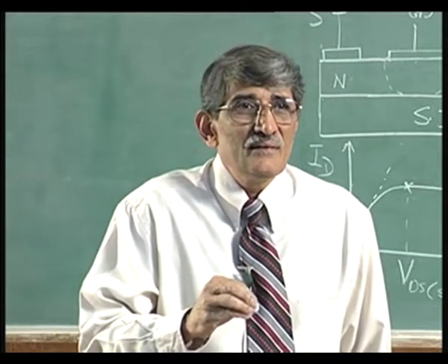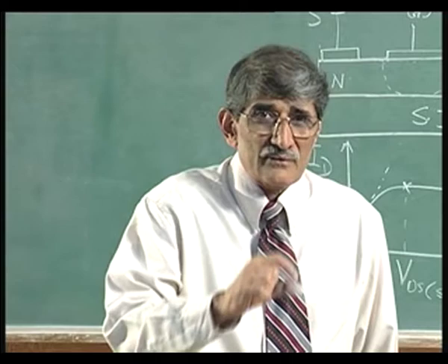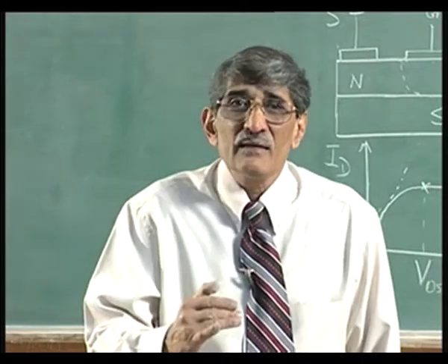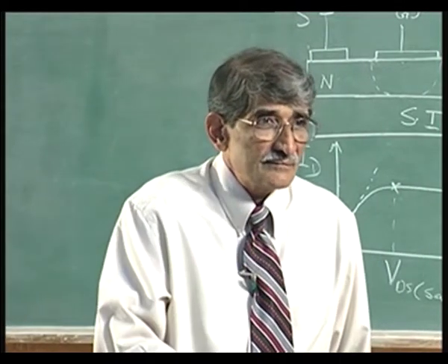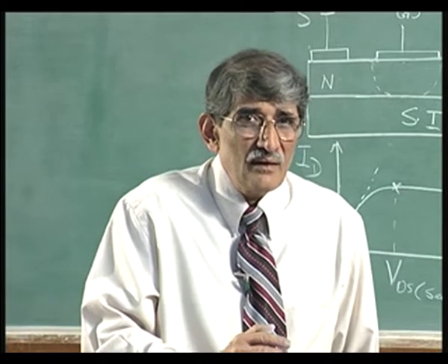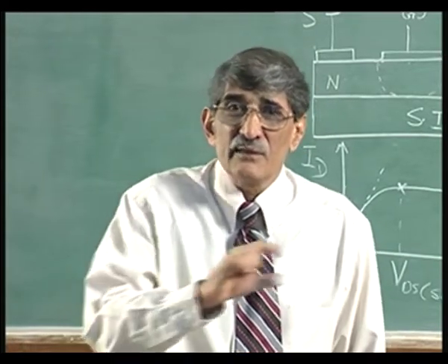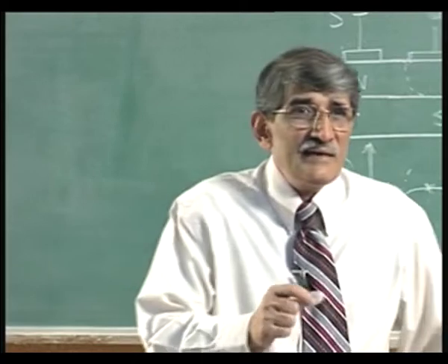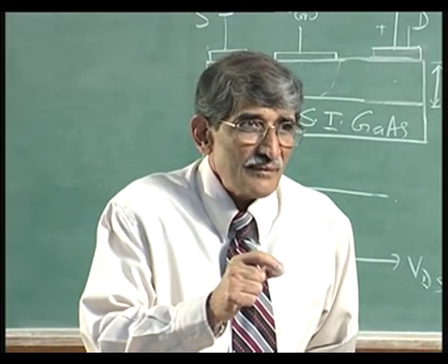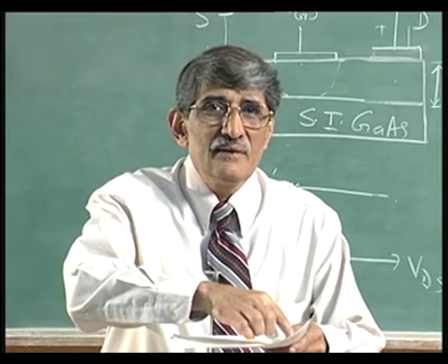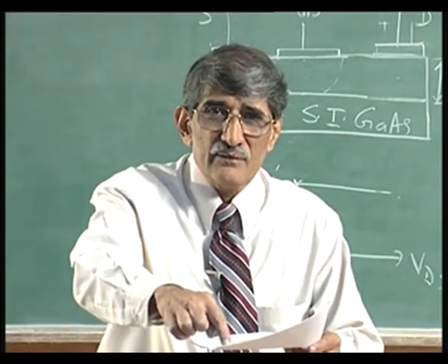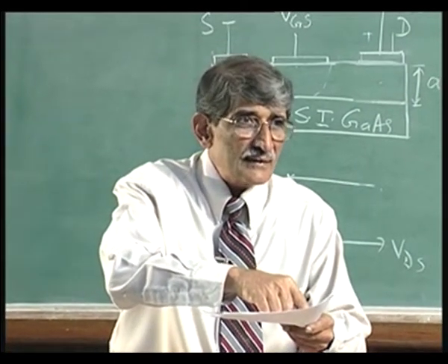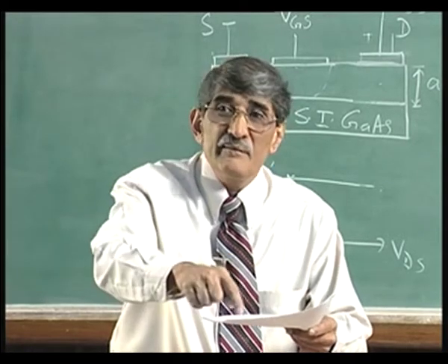So, in the MOSFET, the focus is to reduce the thickness of the oxide, and we will end up in trouble by reducing the oxide to angstrom level. Here the focus is reducing the channel thickness. Please remember, when you reduce the thickness, you must have the reduced thickness uniform everywhere over the entire wafer. Because if A is 0.1 micron in one device over here, I want the same A to be 0.1 micron here. Otherwise, the performance of the device, the transconductance, threshold voltage, etc., here will be different from here.